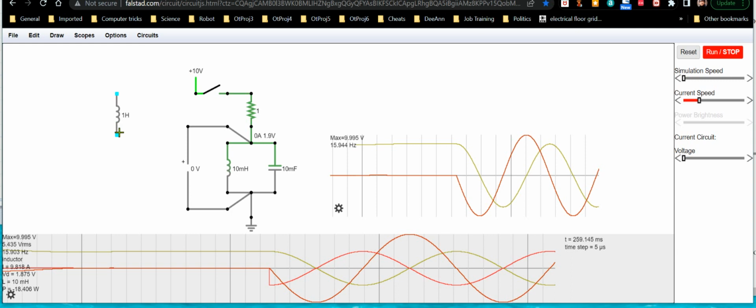Start from the top and move to the bottom, and then I'll hit just C, lowercase c. Do the same with the capacitor. Start from the top, move to the bottom. And of course you can start from the bottom, move to the top, but just do the same thing on both of them to make sure this thing thinks of the polarity being the same. So that's just a word of advice.